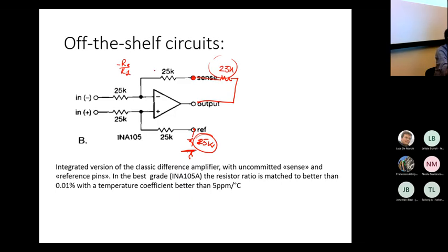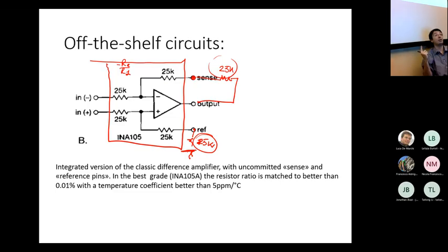When I say that this can be bought in one shot, I mean that all these op-amp plus resistors come in a unique package. Okay, so you buy a discrete component in which the resistors and the op-amp are within the component. Okay, and then you can add additional resistors and connect them to the output pin of the integrated circuit.